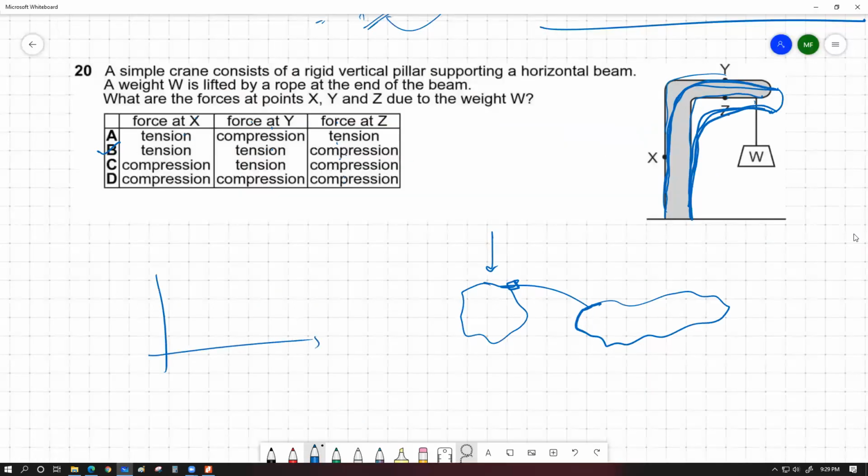Have a look. What happens for the metals? If you consider the force extension graph or stress strain graph for metals, we have a straight line part. At the end of the straight line, there is a P point, which we call the limit of proportionality. Then starts the curve. A little bit into the curve, there is an elastic behavior. Within this curved portion, the force and the extension are not proportional because this is a curved part. But within this part, the deformation is still reversible. Do you get my point?